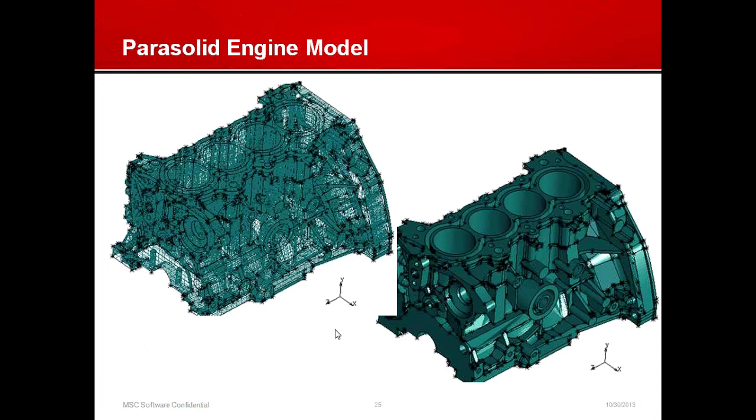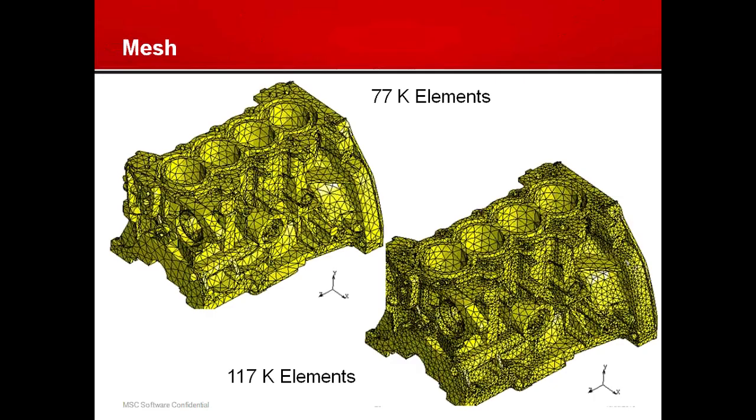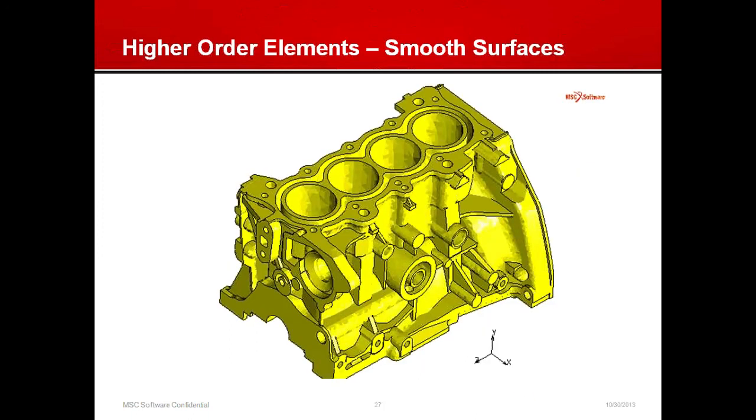You would have had to convert all this into surfaces, then you would have had to add these seed points, then you would have had to match the seed points, and it would have taken forever. Now we'll see that, depending on whether or not you use the default meshing distance or select your own, you can easily generate a mesh.